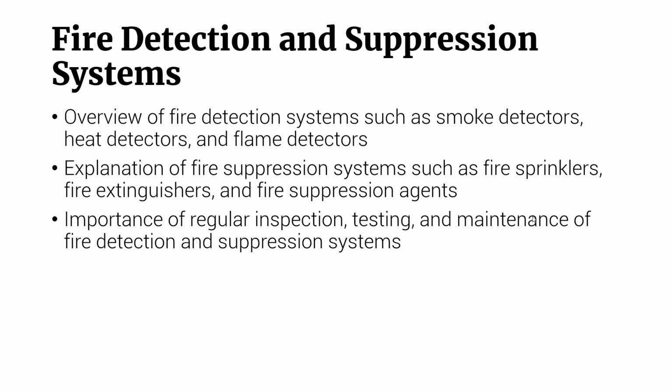We can conduct scheduled inspections din naman, no? And maintenance activities help identify and address issues such as faulty equipment. For example, kinakalawang na yung linya ng tubig mo, diba? Sa sprinkler mo, diba? Yung mga obstructed sensors, yung mga damaged components. So make sure that we conduct regular inspections sa ating mga suppression systems and fire detection systems. Okay?